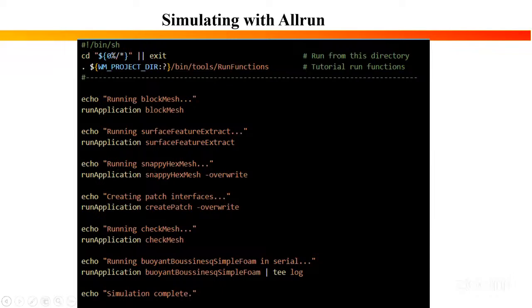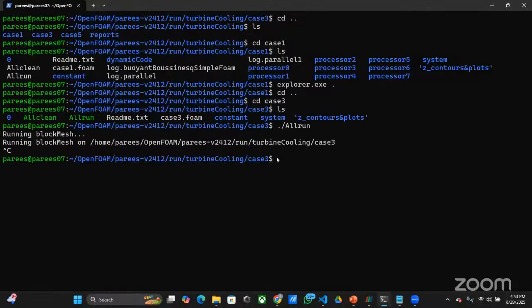Then the third thing is snappyHexMesh -overwrite. snappyHexMesh is a very complicated meshing utility, again provided by OpenFOAM itself. The overwrite option states that whatever you have done previously in your snappyHexMesh, just rewrite it again. For our application, running snappyHexMesh could take around 1 to 2 hours, so I'm skipping that part. I have generated the mesh previously, so I'll show you using my presentation.